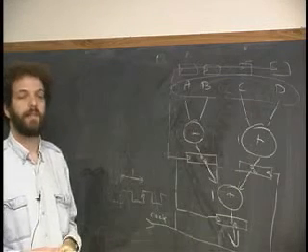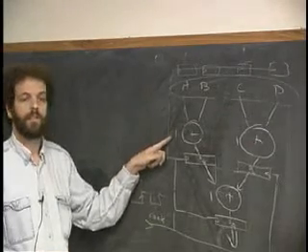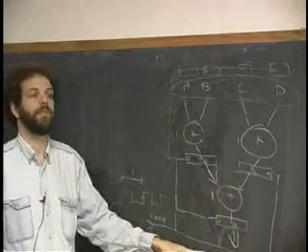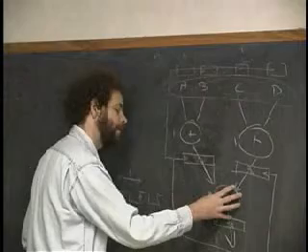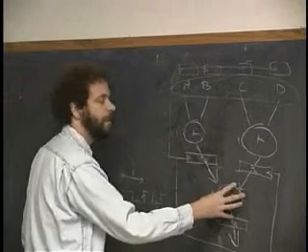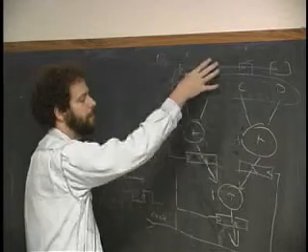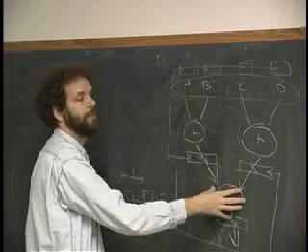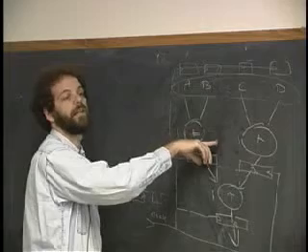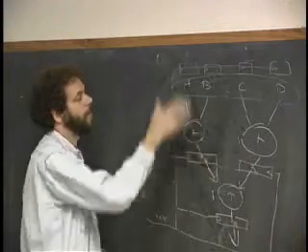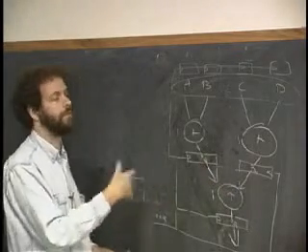But the throughput does get a lot better, right? The throughput here is 1 data item every time unit instead of 1 data item every 2 time units. So we've made that better. It means that the final calculation over here will be done simultaneous with the preliminary calculation for the next piece of data here, just as if this was an assembly line for cars and the finishing was being done here while the painting was being done to the next car in line. So if we have many data items to process, a pipeline circuit like this can drastically improve the throughput.